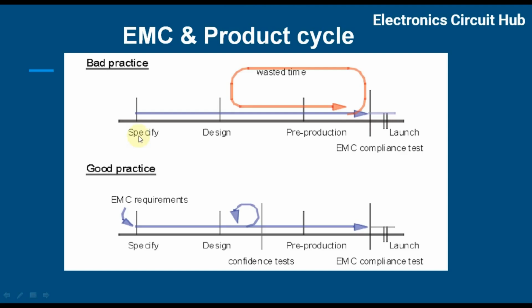So if you don't specify your EMC at a very early stage, what will happen? If you go to the launch stage or pre-production stage, you might need to iterate your design and go back again to the design phase. That will waste your time. And your product may also end up not complying with the EMC test.